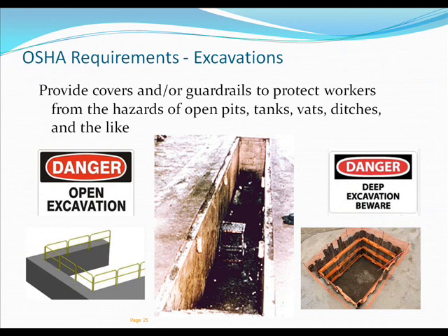OSHA requirements, excavations. Provide covers and/or guardrails to protect workers from hazards of open pits, tanks, vats, ditches, and the like. Each employee at the edge of a well, pit, shaft, or excavation 6 feet or more in depth, not apparent due to plant growth or visual barrier, must be protected from falling.